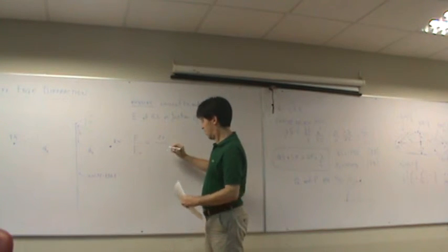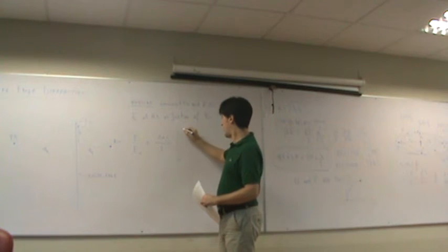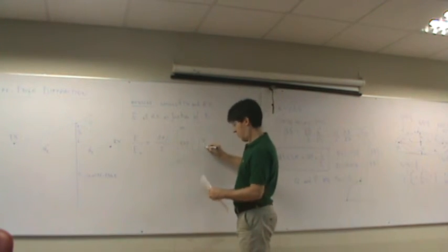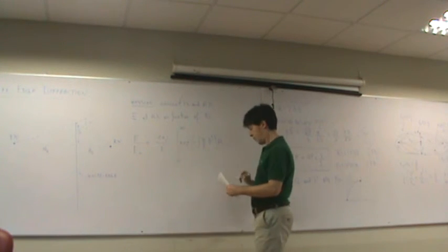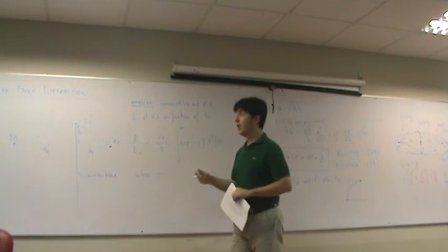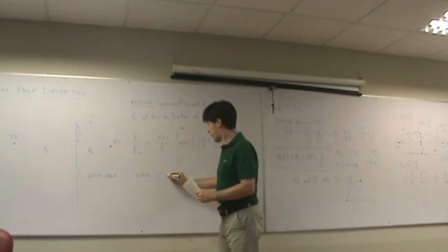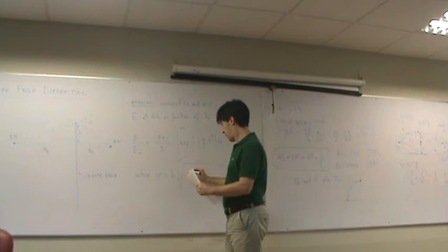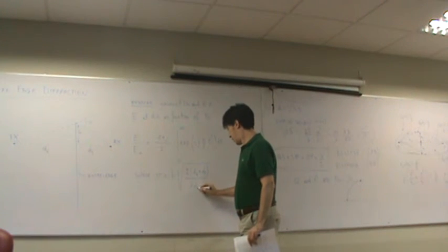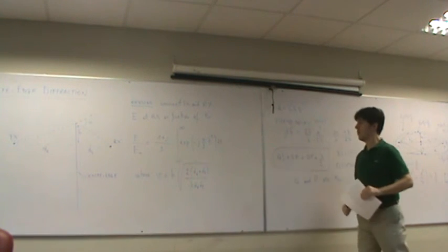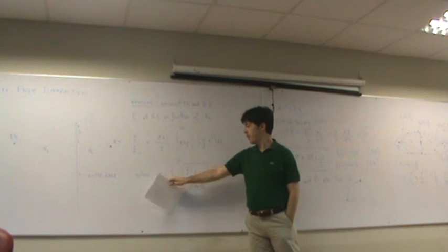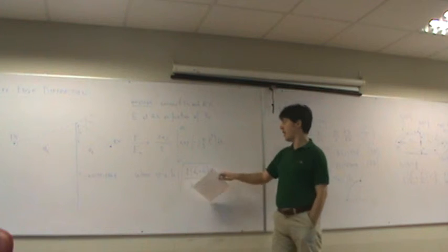I give you for reference, the integral from V to infinity of an exponential, where V is the Fresnel-Kirchhoff diffraction parameter, that is h times the square root of... It's equivalent to the Fresnel-Kirchhoff parameter that we have seen before, just we have replaced rho with h. d1 and d2 are the distances compared.